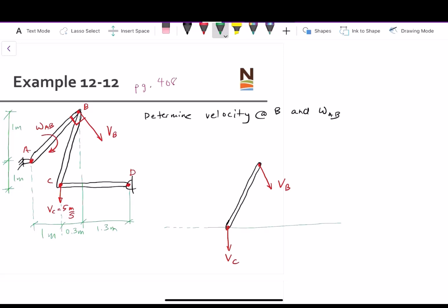So we can see that it's going to be out here somewhere, because I'm going to draw this line. Kind of missed it a little bit here. It's okay. Close enough. So there and there. That is our instantaneous center right there. Point O is our instantaneous center because we've drawn two lines perpendicular to the known velocities, and the point of intersection is that instantaneous center.